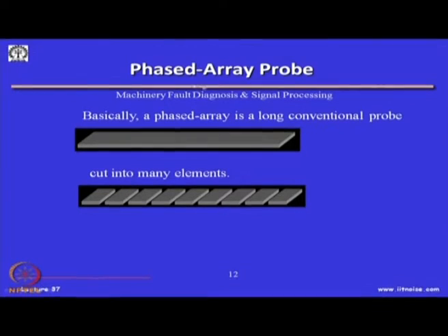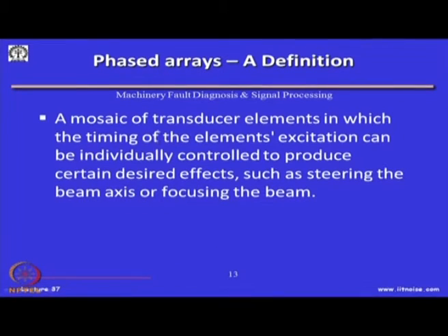So, recently a phased array probe has been made. It is basically a long probe, which is cut into many different piezoelectric elements like this. In phased arrays, the timing of each element's excitation can be individually controlled to produce desired effects such as steering the beam axis or focusing the beam.